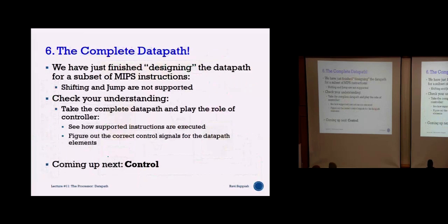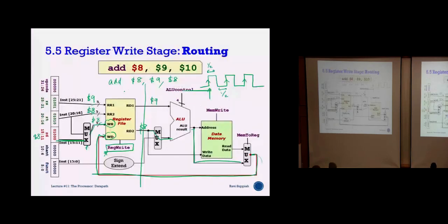So this basically covers the whole processor, except what we have not covered: the shift instruction and the jump instruction. Where is shift and jump? Shift is actually here, correct? If you look at your R-type instruction, your shift amount is specified as bit 10 to bit 6. So if I want to implement a shift, I now need to look at these shift amount bits and then pass them through a shifting block. That will give me the final result.